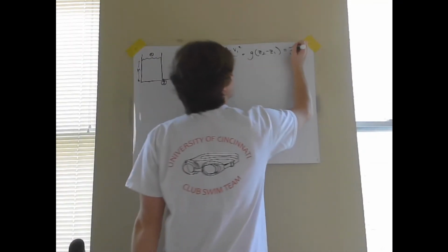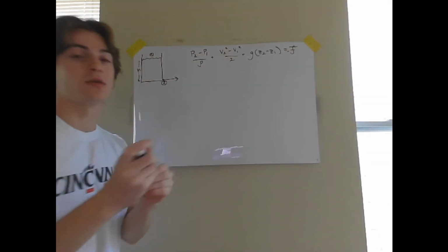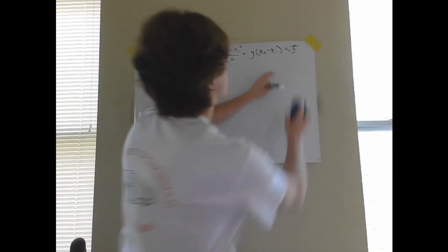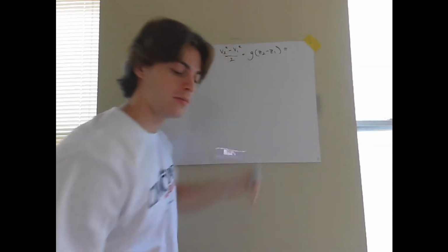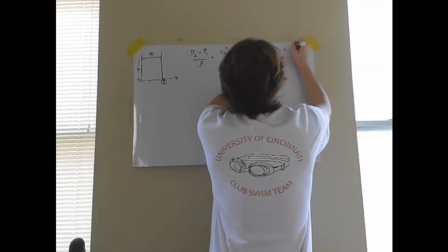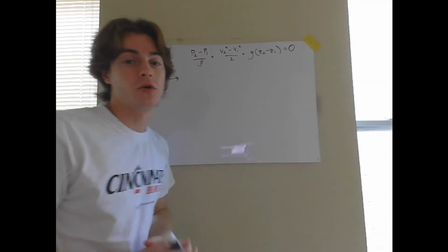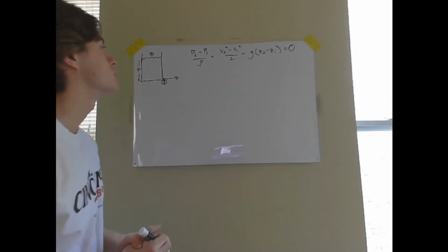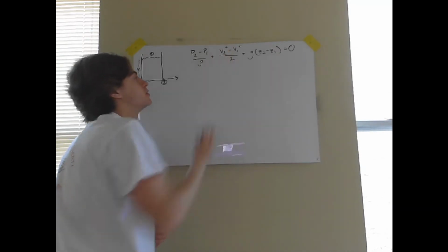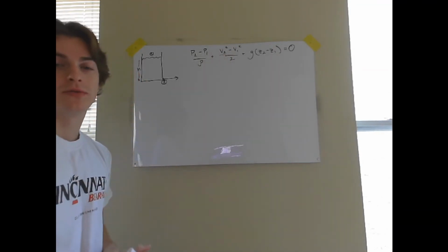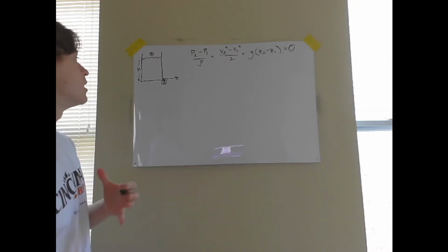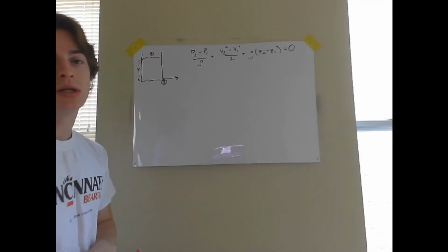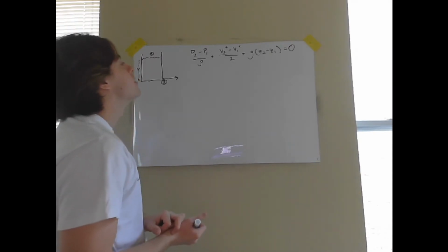So in this problem, we're going to go ahead and ignore frictional heating. And so the right side of the equation is just going to be 0. And that simplifies the problem a little bit. We will have to incorporate it in our expression later on. And so basically the goal of this is we want to find an expression for V2. Because once we find the expression for V2, we'll be able to get the volumetric flow that's coming out of the hole, and we can use that to model the change in height in the tank.